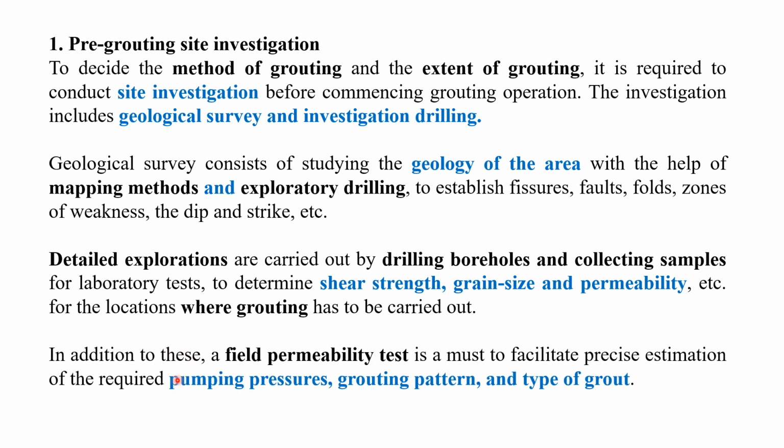In addition to this, a field permeability test is a must to facilitate precise estimation of the required pumping pressures, grouting pattern, and type of grout. So these 3 things, field permeability test, as you know, pumping in test, pumping out test. So depending upon the test, once we find out the permeability in the field, accordingly we can decide what should be the pumping pressure, what should be the grouting pattern, and what should be the type of grout which can be used at a particular site.